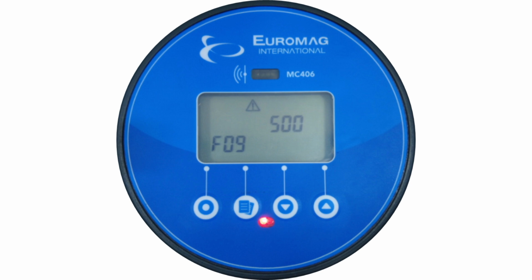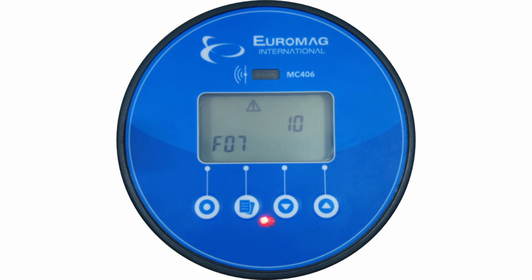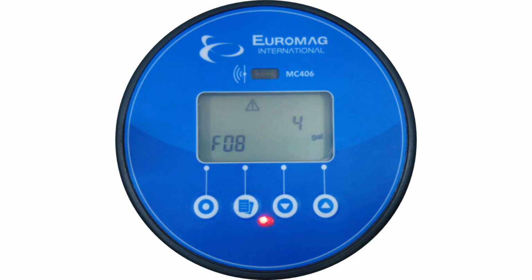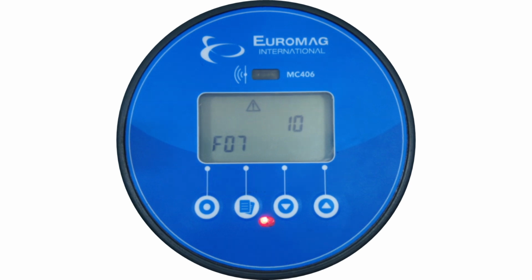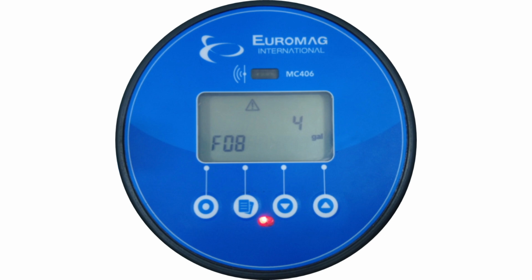In summary, function number 7, number 8 and number 9 are used to set the pulse outputs. Function 7 sets the pulse volume, function 8 sets the pulse units and function 9 sets the pulse width. This converter will send one pulse that lasts 500 milliseconds every time 10 gallons pass through the sensor body.